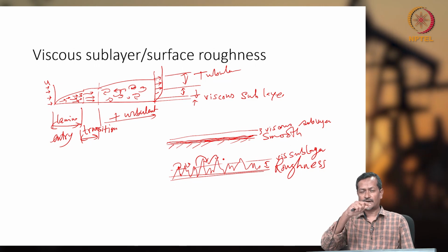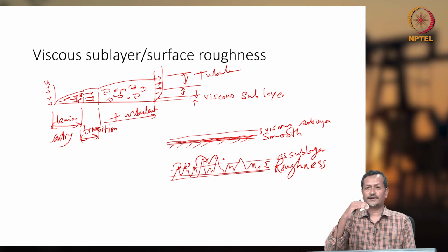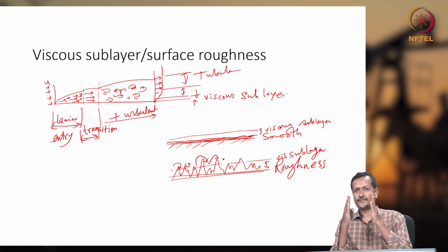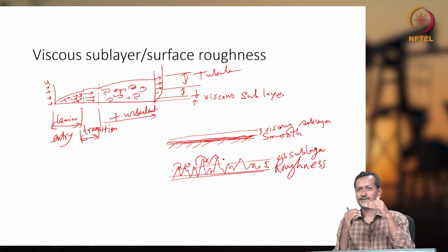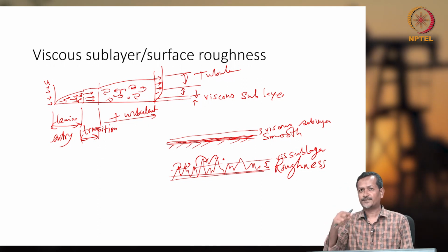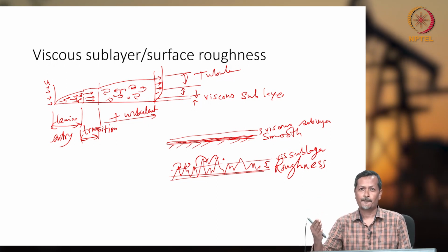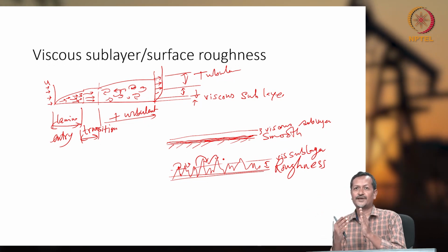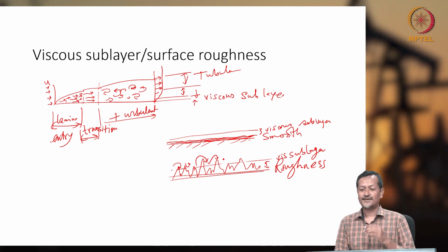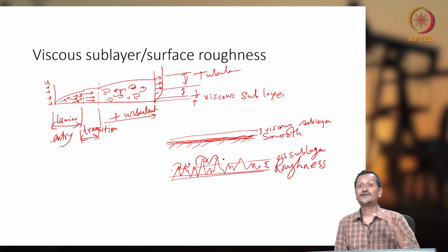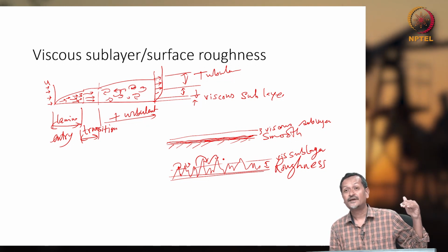When a fluid particle likes to move on a smooth and straight path and it gets some stopper, say ridges or valleys, what will happen? The fluid will move up, sometimes down, sometimes up and down. Because of moving up and down, it will lose energy and lose its velocity. So the fluid will get more resistance, and the pressure drop will be much higher. A rough surface gives more resistance, so the fluid will not be able to flow smoothly.